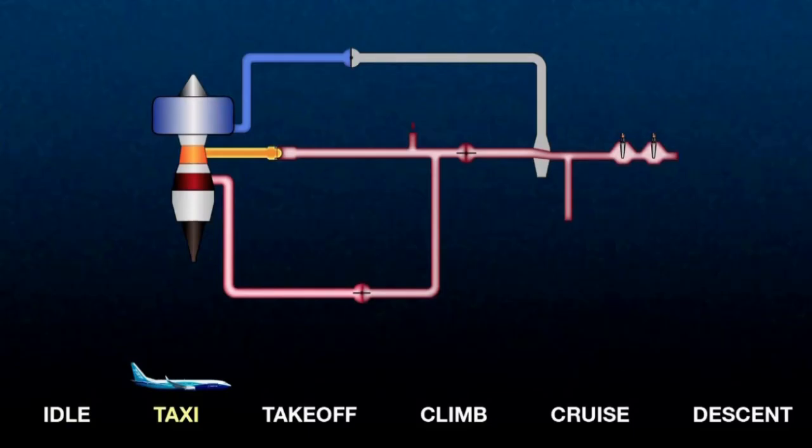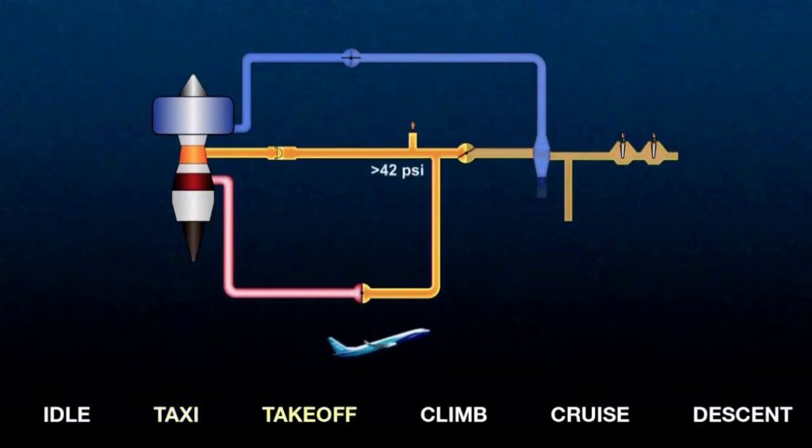Depending on throttle setting, the pressure may rise above 32 psi. If this happens, the HSV will act to regulate the pressure to 32 psi again. Depending on the throttle setting, the bleed air temperature may rise above 390 degrees Fahrenheit. If this happens, the PCCV will open to keep the bleed air at 390 degrees or below.